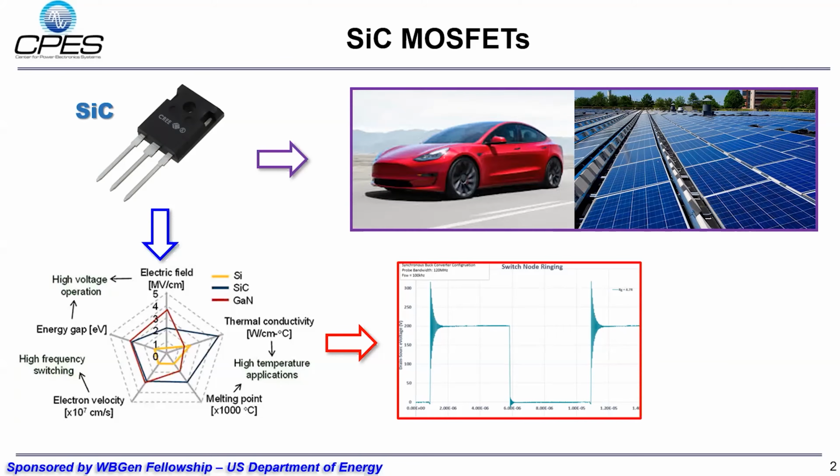The drawback of this higher switching speed is caused by the internal parasitics of the device, mainly the capacitance and inductance, which during rapid switching will cause significant overshoot and oscillation for both turn on and turn off. This overshoot is undesirable because it causes the devices to be derated so the overshoot does not exceed the maximum rating of the device. Also, with a high switching frequency, the di/dt increases, leading to more EMI being generated. This means that additional EMI shielding or mitigation techniques must be used, and this can lead to a larger, more expensive system.